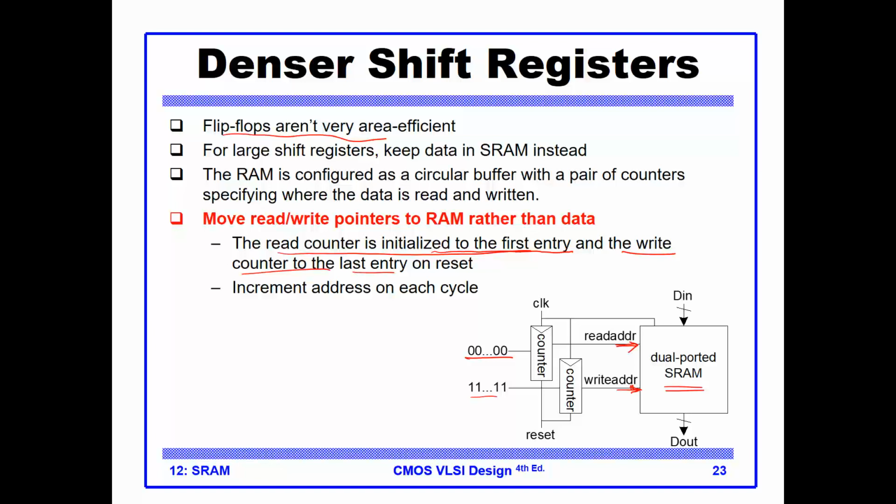Okay, and you can think of this more as a circular FIFO. For instance, you can think of this FIFO as a circle, like so. Let's say, for example, here, this is address 0, 1, 2, 3, 4, 5, 6, and 7. So for instance, suppose I pushed data which is A, B, C, D, E, F, G, H, where this is the earliest and this is the last.